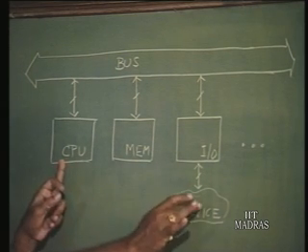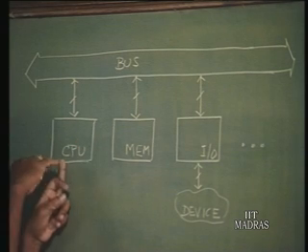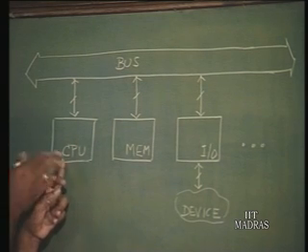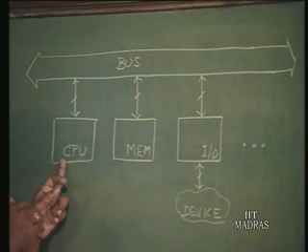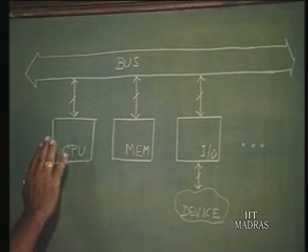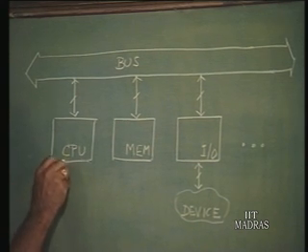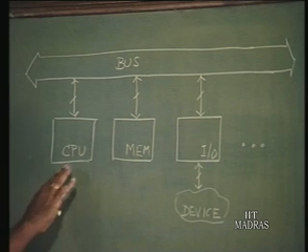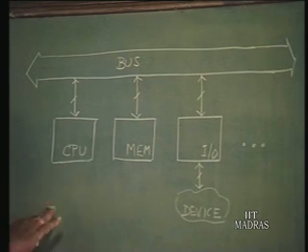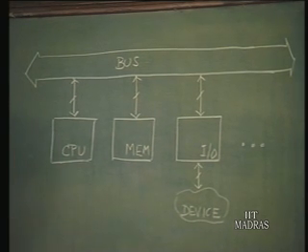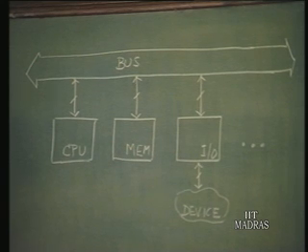At the end of that interrupt service, the processor must continue with whatever it was doing earlier. That is, it is something like switching back from the subroutine to the main routine. So, the necessary information for that must have been stored earlier, prior to switching over to the other context. That is going to cause some delay, that is number one.